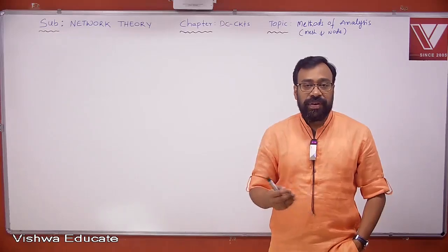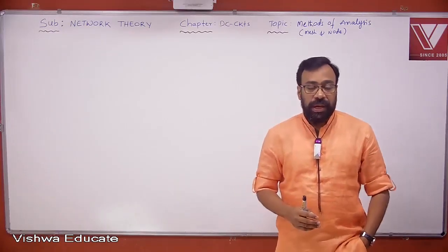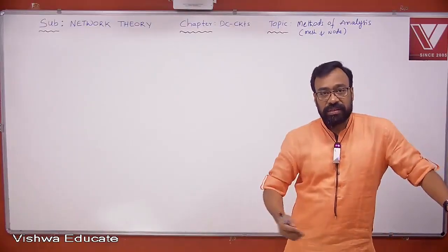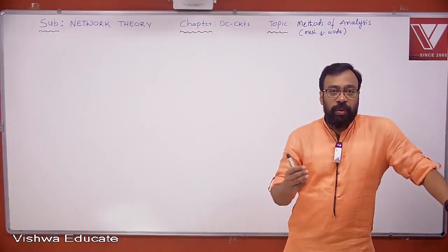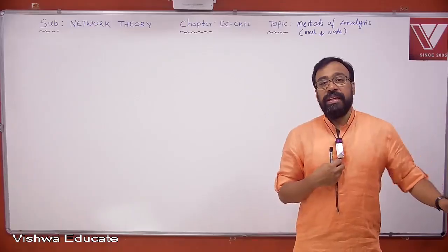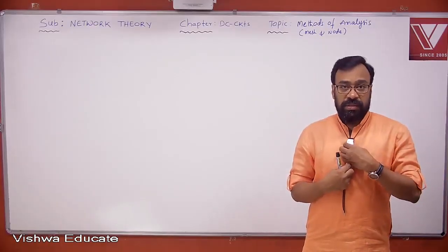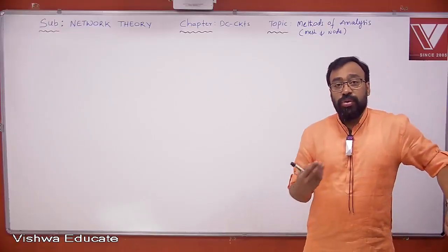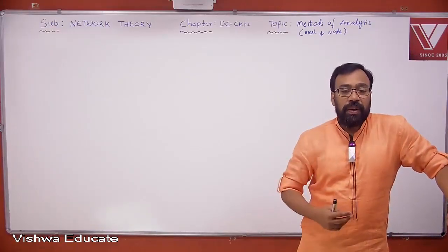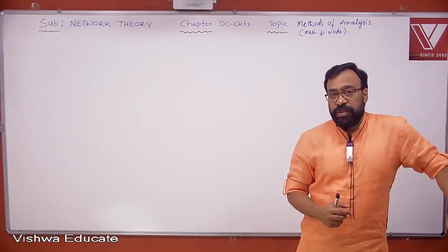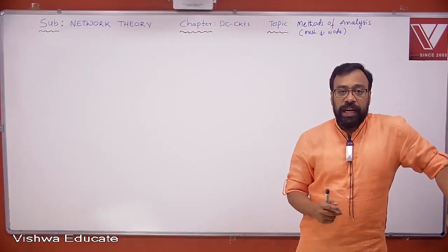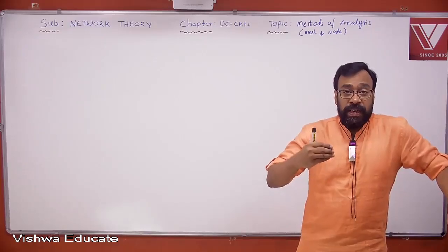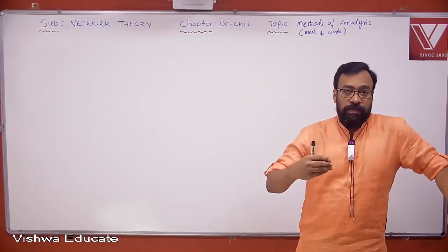Node analysis, reference node shifting method. Yes or no? Okay. And I told you already that the reference node shifting method will be very much advantageous in most of the cases, especially when you have ideal voltage sources without any series resistors. Without any series resistors, you can do the problems easily with fewer equations with the help of the reference node shifting method. Okay. And now we are very much comfortable in finding the minimum number of equations required to analyze the given network.